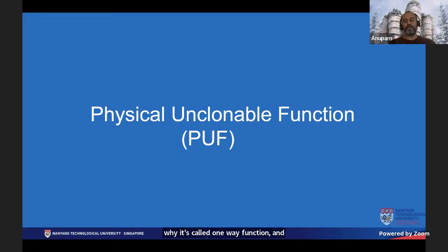And it's also considered unclonable. That means if you don't know the exact circuit structure, then it will be impossible for you to replicate this in another form. And the exact circuit structure, from where the unclonability properties are derived, is based on some manufacturing variations, which makes it very difficult for someone to actually recover all the intricacies of the circuit without destroying it. So that became a very important structure that people started using for fingerprinting devices. In one sense, you can consider physical unclonable functions or PUFs as a device-level fingerprint.